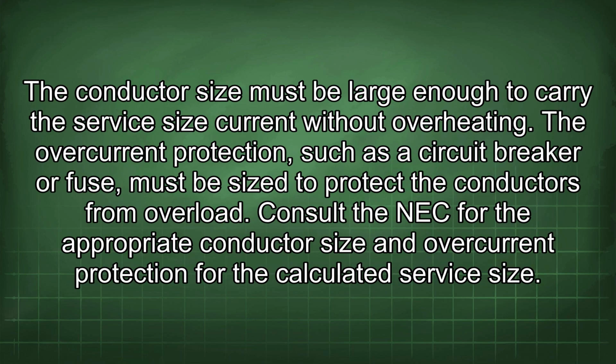The conductor size must be large enough to carry the service size current without overheating. The overcurrent protection, such as a circuit breaker or fuse, must be sized to protect the conductors from overload. Consult the NEC for the appropriate conductor size and the overcurrent protection for the calculated service size.